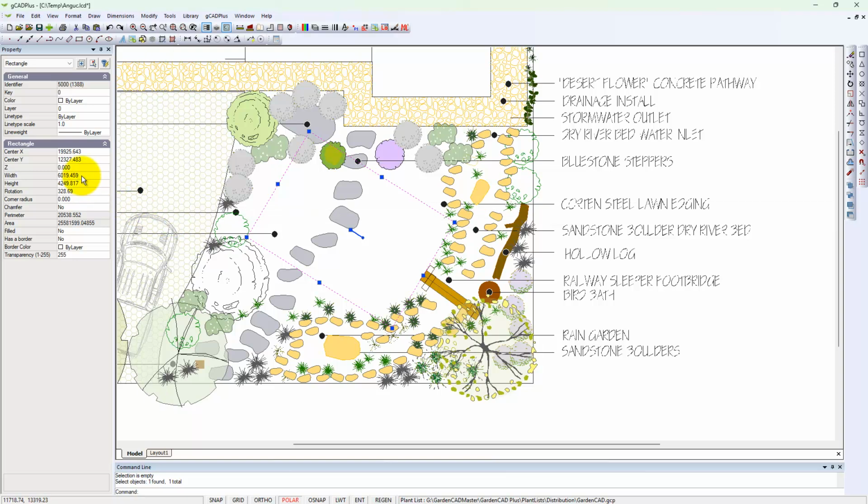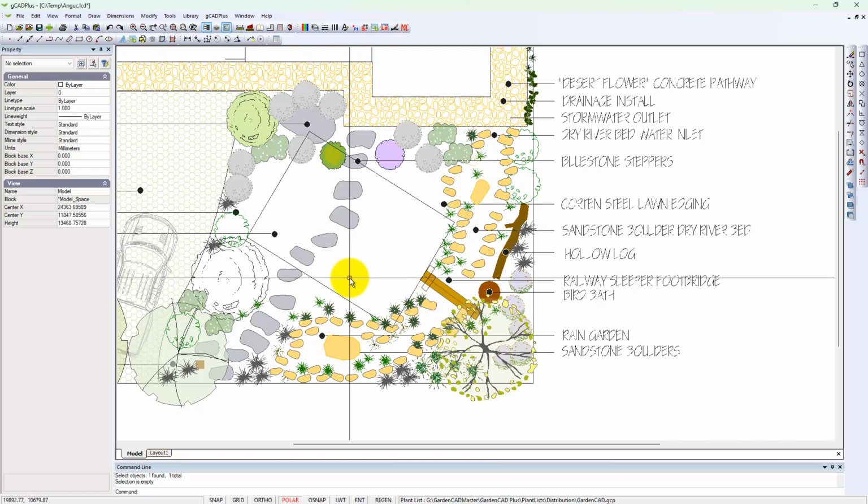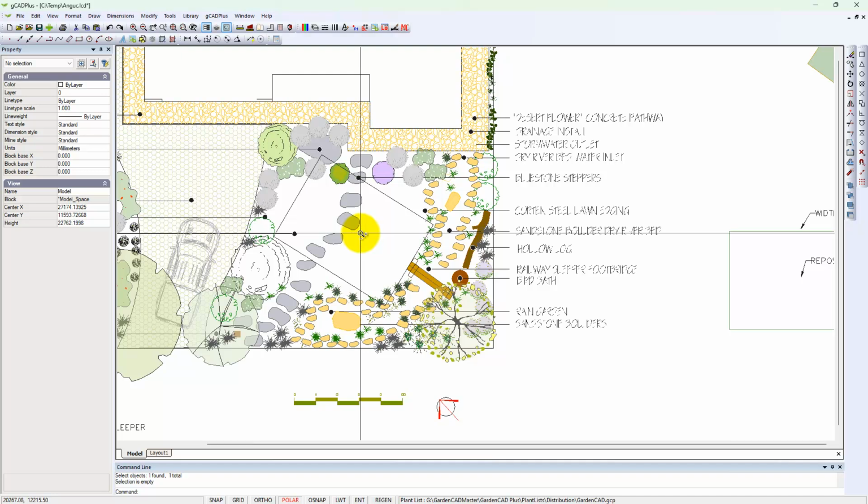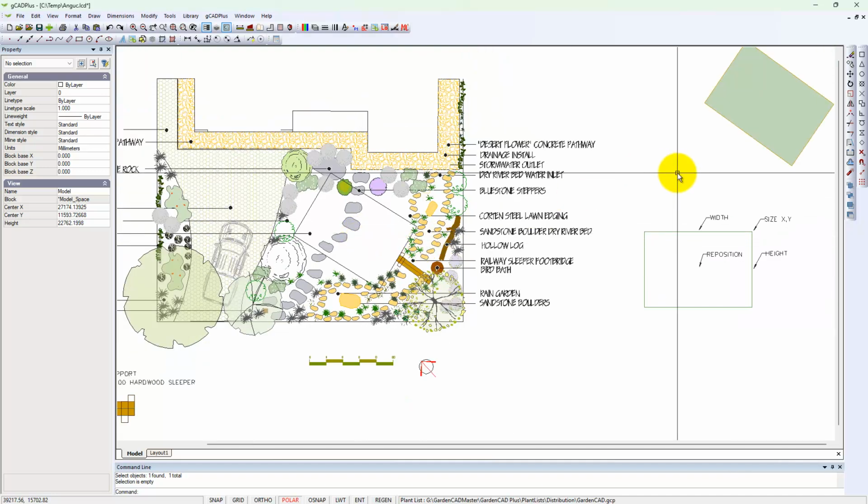What I would do at this point is round those numbers off. The width, it's 6019. This is in the metric area, but the same applies in the imperial or US area, 6010. That makes it a little easier. And then 42, so we want 4250, 4250. And now we have a lawned area that's easy to peg out for our construction team.